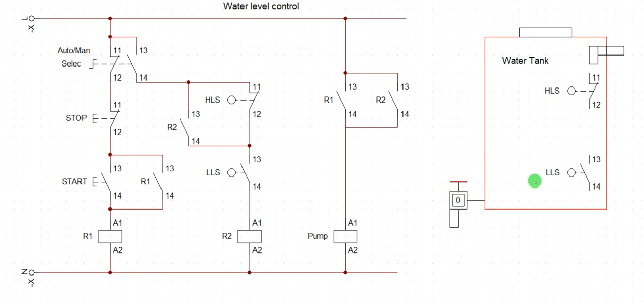So when water gets to this level, this one will cut and shut down, and they activate this. Then water starts filling. When water starts filling and gets to this level, we activate this to stop the pump from pumping. So these are the two limit switches. Look at them here. Watch these two switches, how they change state when this original switch is activated. I just put them here so that you know that this one is representing this one and this one is representing this.